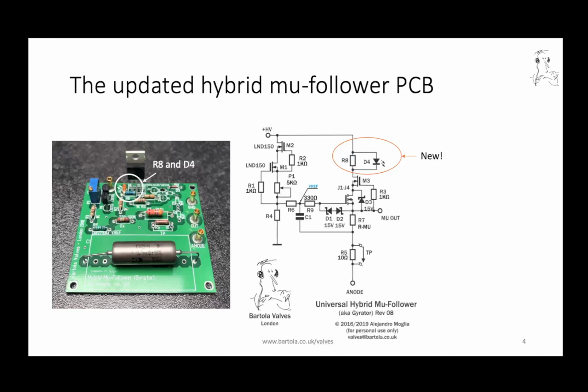Of course, if you add a very big resistance, then the challenge you have is that the power dissipation requirement is very big, unless we're driving a very low current triode, for example. But anyhow, in normal cases, somewhere between 100 to 200 ohms, that's what you're going to end up with.